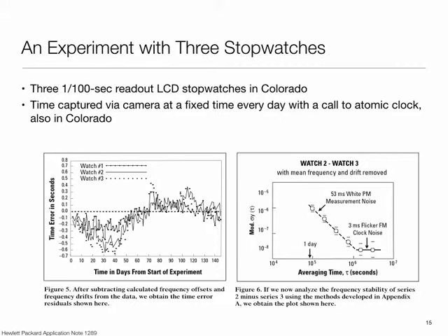So you can say, okay, maybe I should use that. The problem is that if the time at which I have to be woken up is way in the future, then as these plots are showing, the frequency is going to go through lots of changes. Because of environmental conditions between now and 5 p.m., which could be hours or days from now, the clock may have become slower, and therefore I would miss my deadline because I would have counted the ticks according to a wrong impression of frequency.